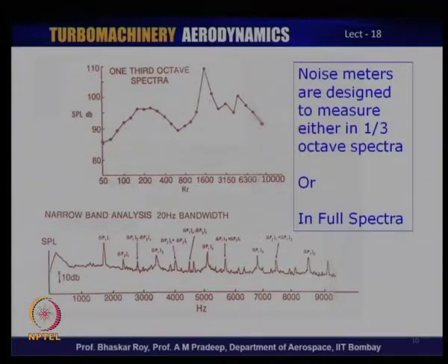That is the overall RMS of all these frequencies averaged very quickly and given as one single value in dB. Whereas, as you can see here, at various frequencies the dB levels or SPL levels are different. At some frequencies the dB is lower, at some frequencies the dB is very high, and those are the annoying noises which need to be somehow cut out, and the engine designers and the containment people have to work out how to cut out those noises which are coming from particular frequencies.